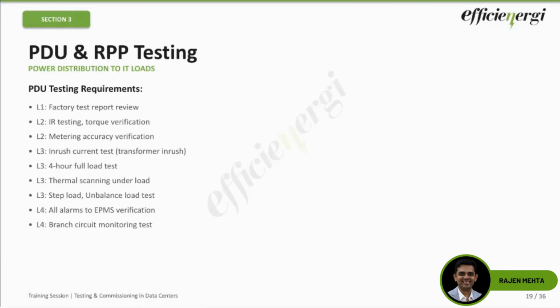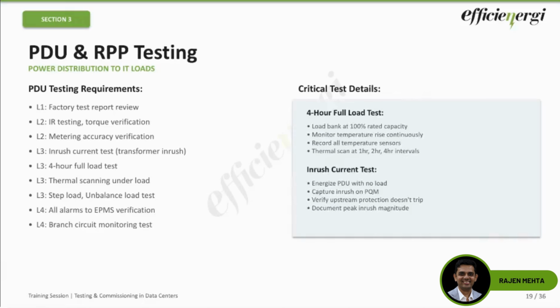Obviously you will want to monitor various things: your temperature, your currents per phase, your voltage stability. What you want to look for is uneven temperature rise between the phases, if at all. Hotspots when you do the thermal scanning, and temperature exceeding the limits, right?